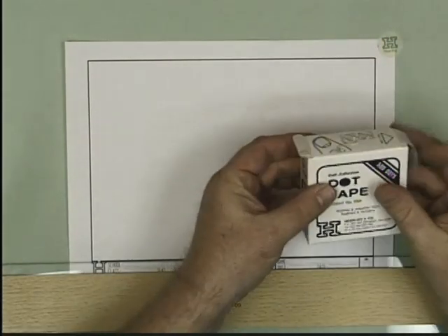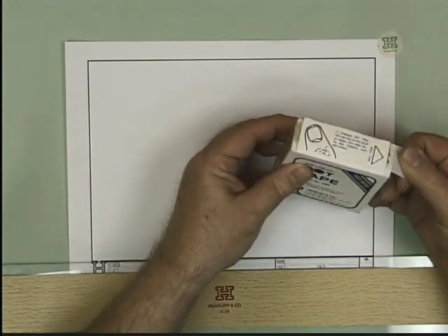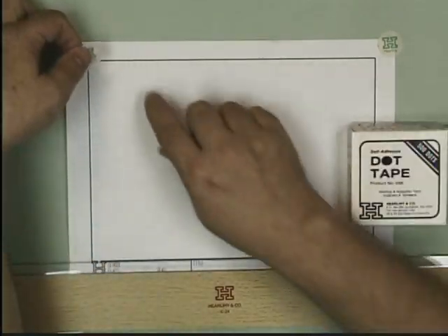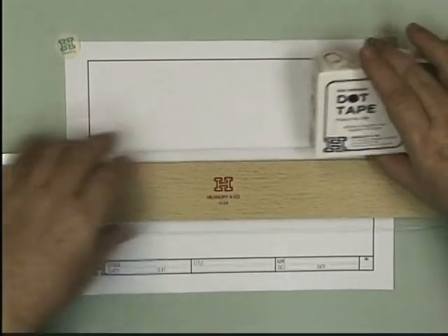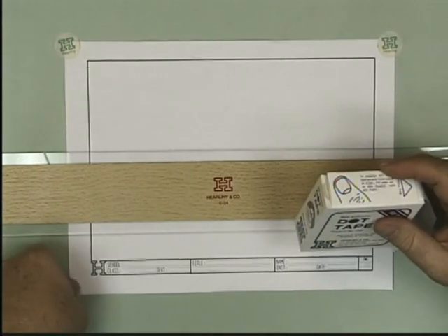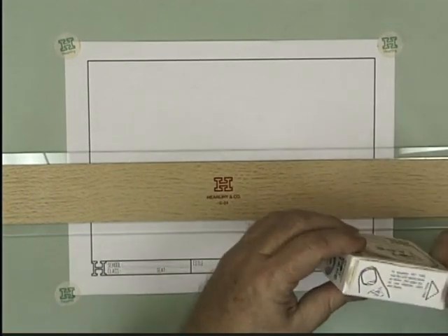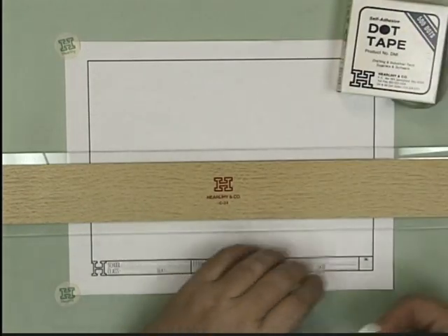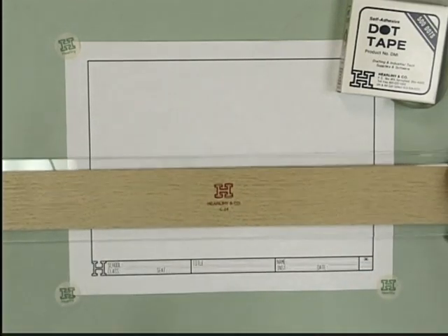This is like a little dispenser pack. When I pull on this tab a little bit, you see it sticks its tongue out at me, and I can take the next tape dot. And I'll apply one to each of the four corners of the drawing, with the drawing carefully aligned to that T-square, especially when I do the first two, because that will establish that the border of the drawing is aligned exactly to the T-square.